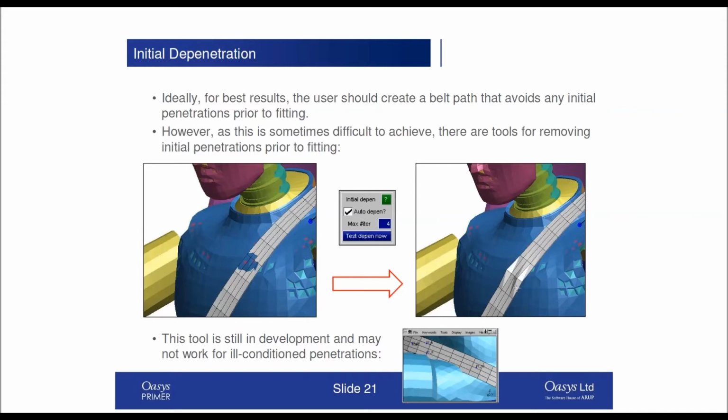affect the final form. This would be essential if you did have crossed edges, because crossed edges basically ruin the belt fit. Just like in an LS-DYNA analysis, it snags the belt contact and the belt can't be pulled correctly anymore. It's worth noting that we're still developing this tool, and there are some geometries where it doesn't work so well. That's where you've got this edge-to-edge type contact there that we see at the lap. It's worth trying, but it's not as robust with that type of contact.